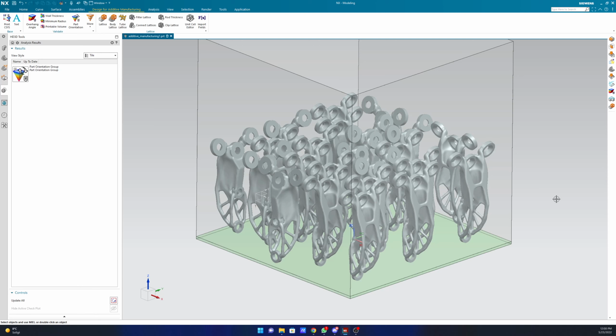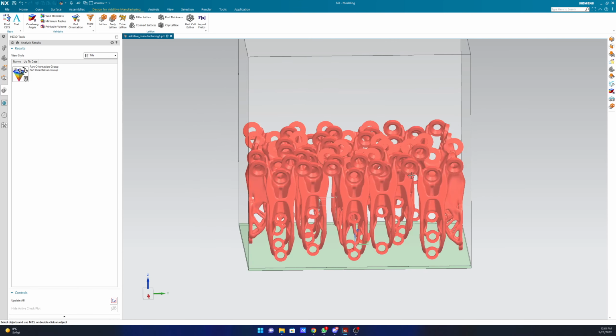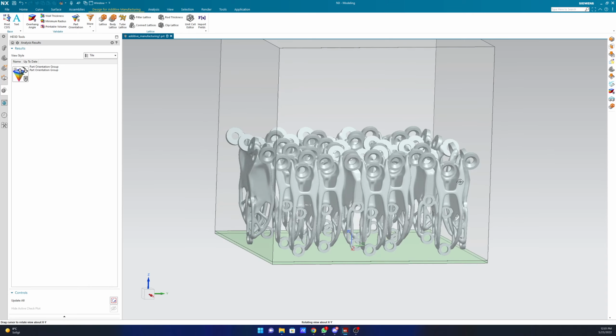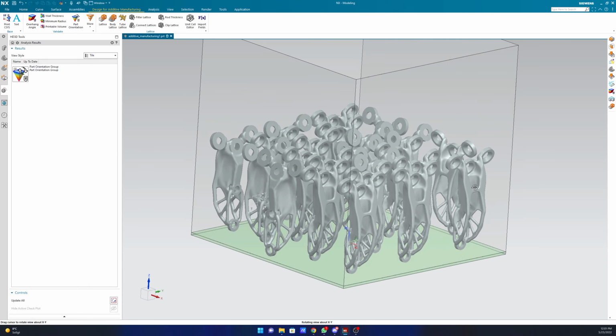Maybe due to some post-processing operations. The thermal stress will be low, right? I think it will be higher because only one part is touching the build plate, and it's like an inverted triangle here, and we don't need that. The temperature gradient will be higher, you are suggesting.